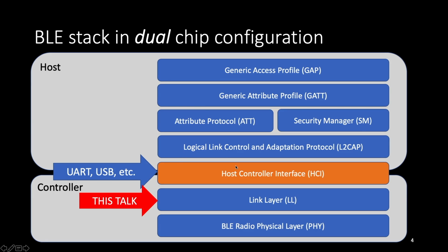Through the HCI, the host generates HCI commands to the BLE controller, and the BLE controller generates HCI events to send the result back to the host. And when you receive BLE packets, it also generates HCI events to the host.